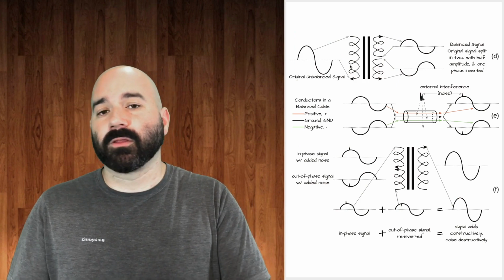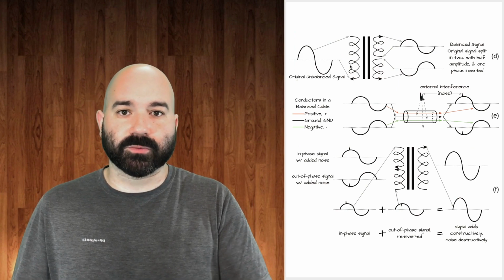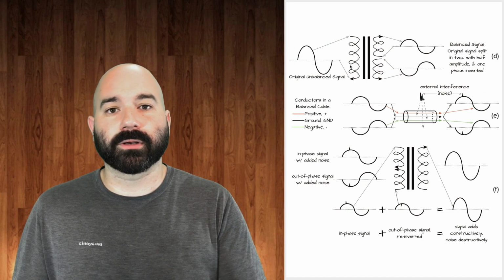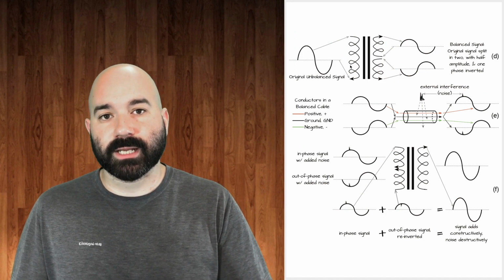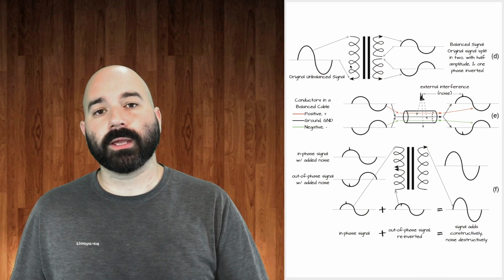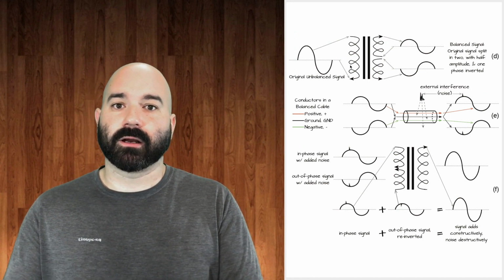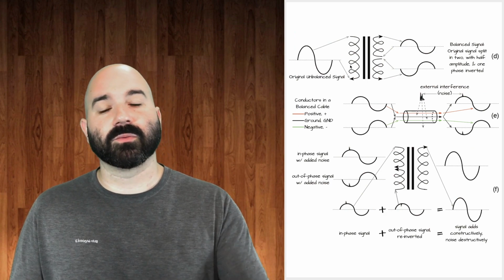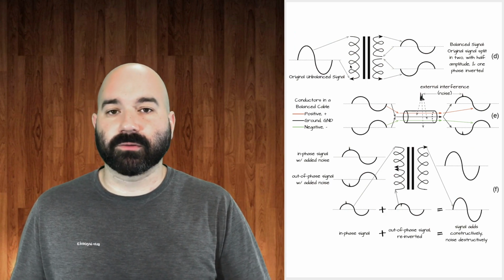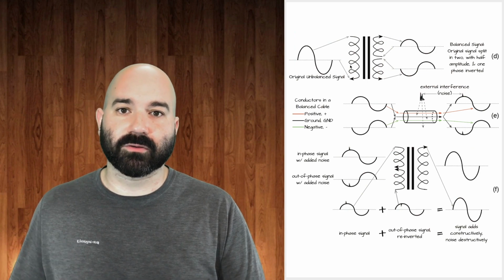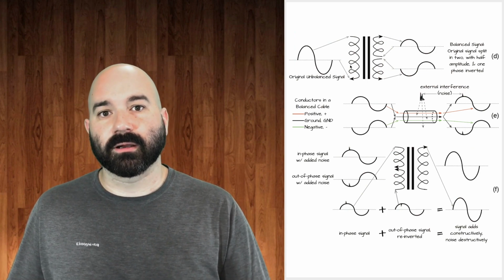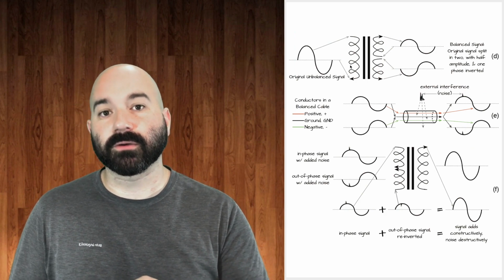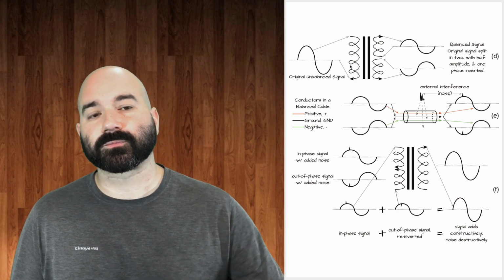Now, sometimes the markings rub off, or not all manufacturers print it on there, so then what? Then you just go look at the manual, and again, it's all about learning what device you have and understanding it. And so you can't connect an unbalanced guitar signal into a balanced connection and expect that you will have this phase cancellation of interference. You have to have a balanced signal from the source and being summed up together at the end. And again, just look for the labeling on that.